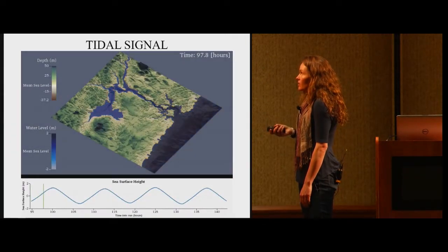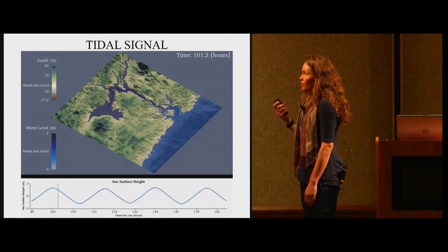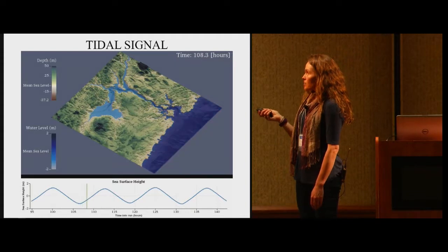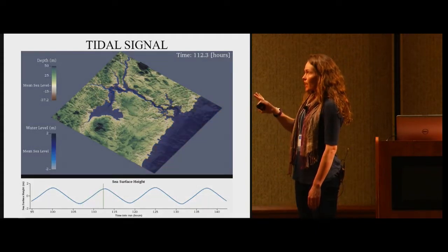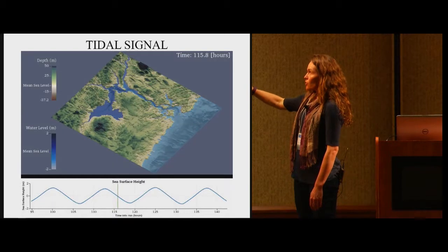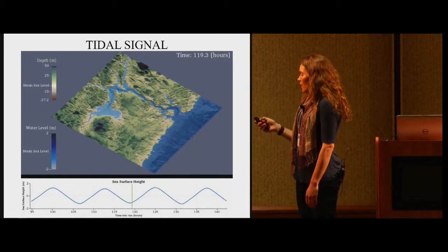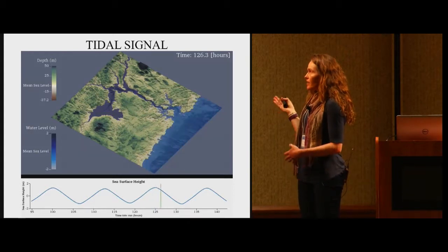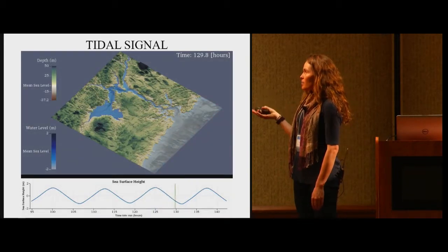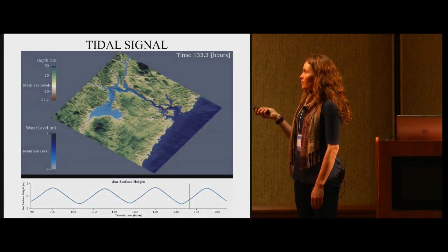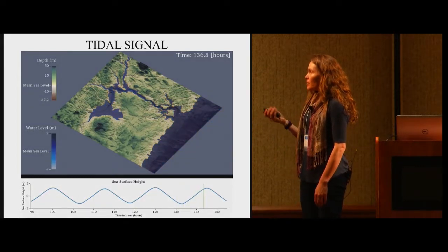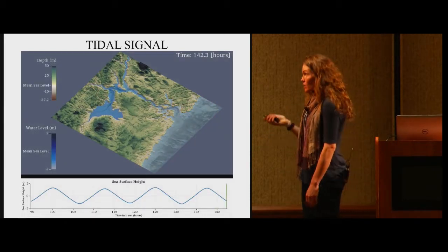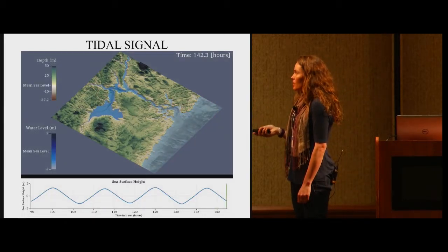So this is a video in ParaView of the tidal signal from data that we collected using Blue Waters. You can see that as the tide comes in, those are those darker colors, it fills the entire estuary, and then you have draining on the ocean before you have draining in the bay. There's about a 2.5-hour time lag between tides, high tide in the ocean and high tide in the bay. You can see at low tide those sort of wetting and drying. The model is getting that, which has been a numerical issue in a lot of other ocean models. And it was only implemented in 2013.